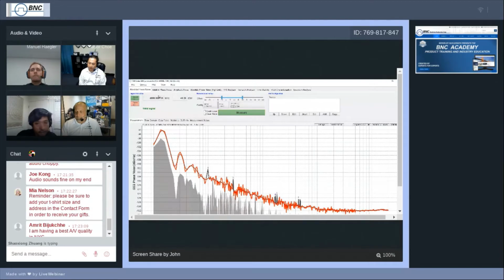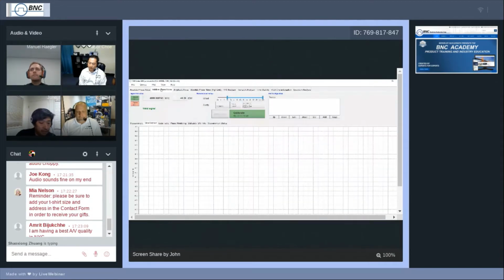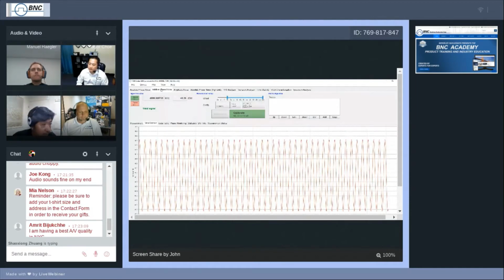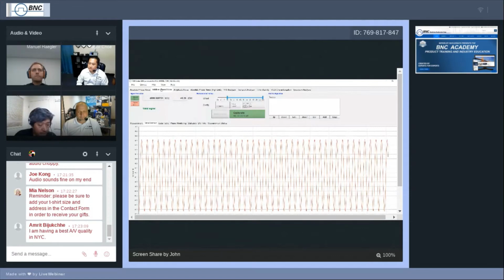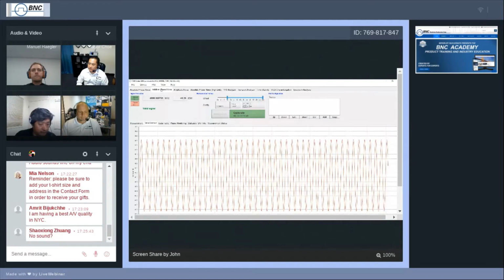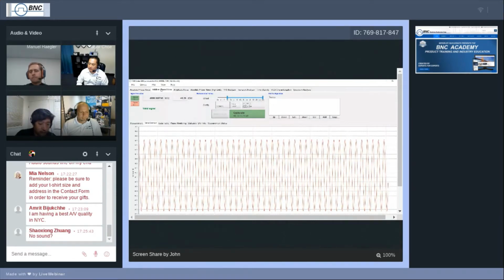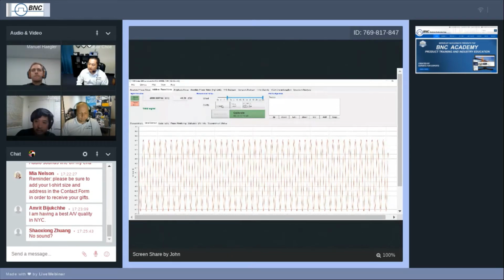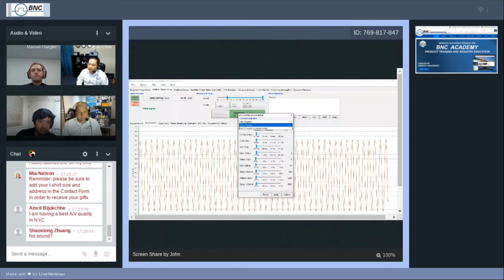The second tab is the additive phase noise, or commonly known as the residual phase noise. Again, as Junior said, this is for non-oscillating devices like a low noise amplifier or passive devices like attenuators and cables. With additive phase noise, you will need to decide whether you use a one channel or two channel cross correlation. A two channel cross correlation will yield a lower phase noise floor. Let me set that one up.